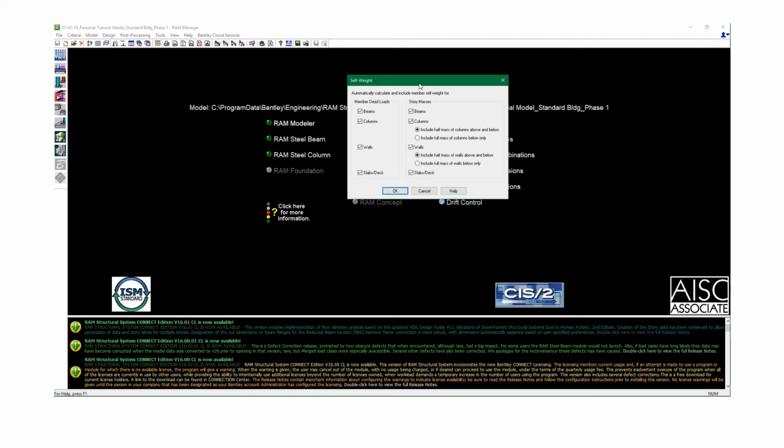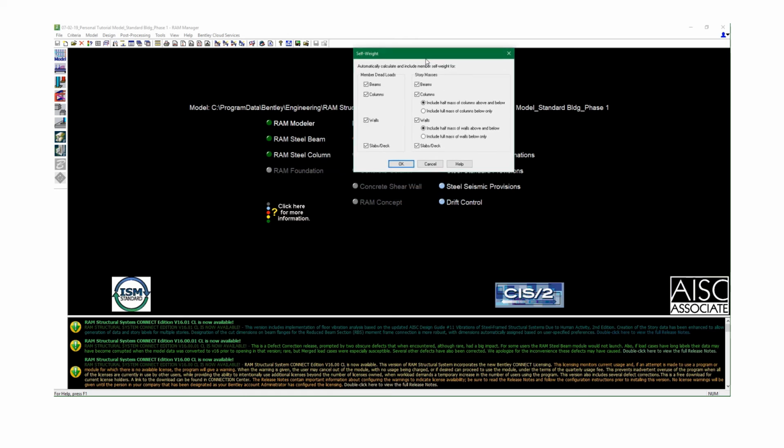That's for the lateral frame resisting system. Some people may view it differently for the foundation itself, especially if your foundation is on piles. You probably want to make sure you include all of your forces, all of your mass from above, if it's on piles. And I would say even more specifically, if you have the first layer into the ground of the piles, if you will, from the ground to the point of fixity.